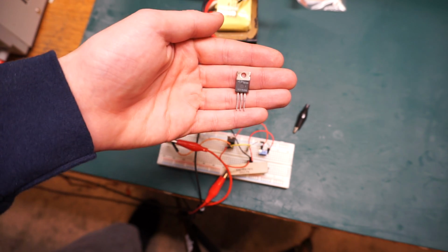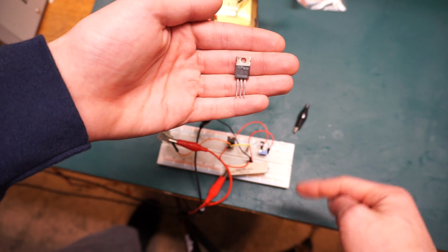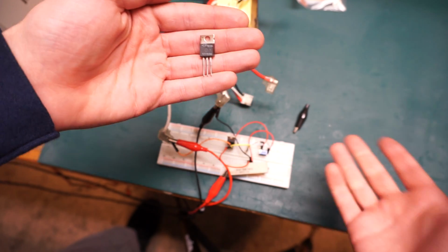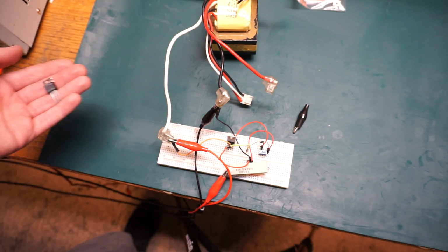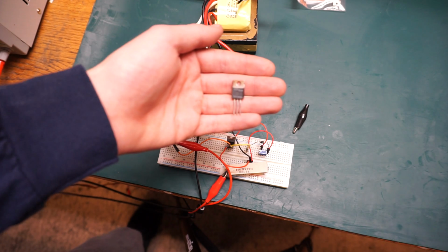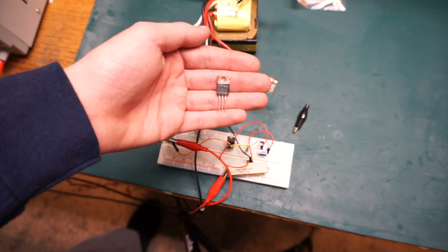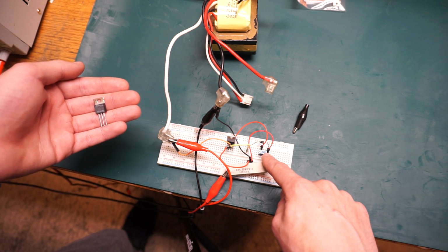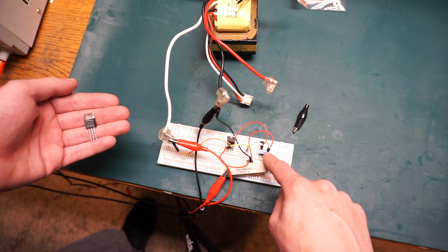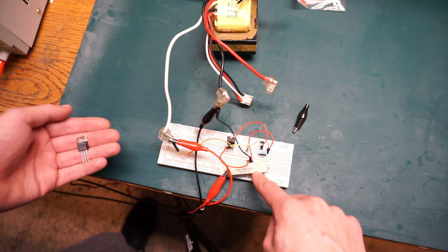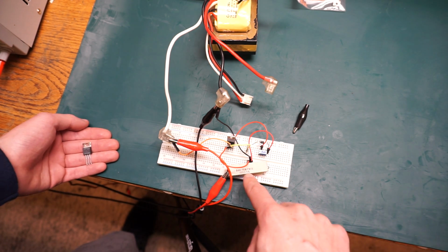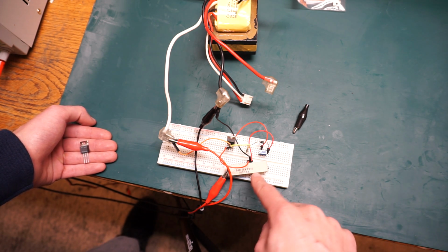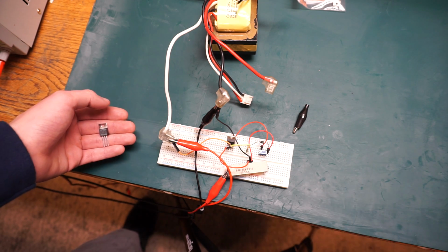So I have that circuit that I drew on the board earlier for that phase control. It's hooked up. I'm not going to really show you guys the breadboard, because you're not going to really be able to follow it. It's what I drew on the board earlier, pretty much exactly. So we just have one of those little jelly bean diodes. Here is a 10K little trimmer pot, and here is a load resistor. This is just a 100 ohm, 15 watt load resistor. It's just a wire wound resistor.